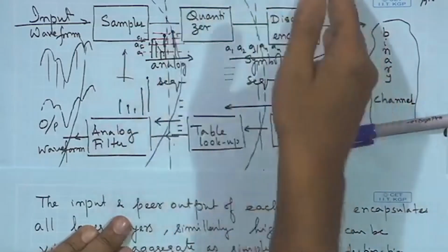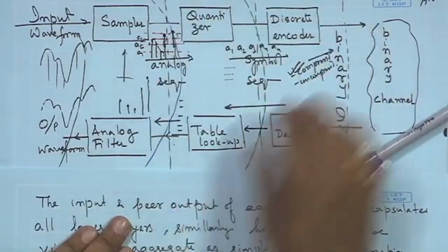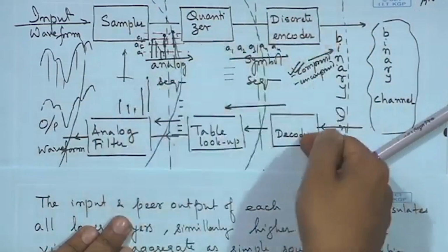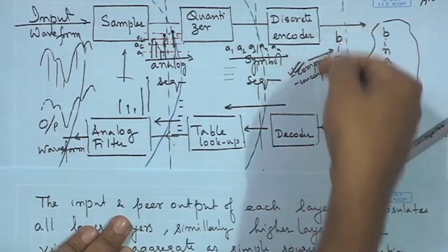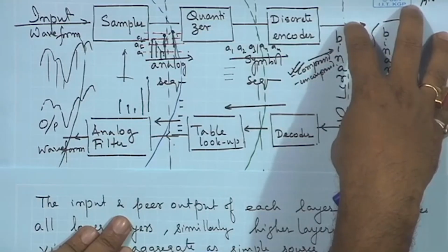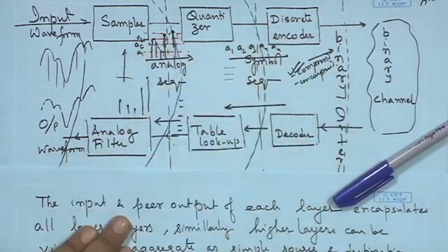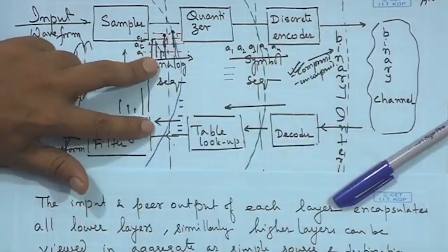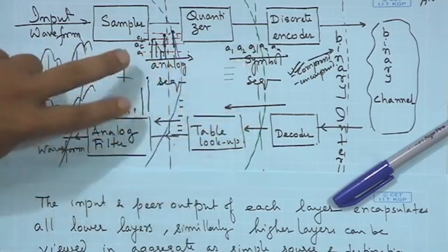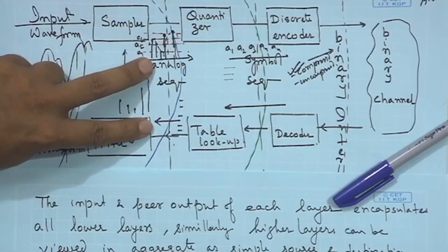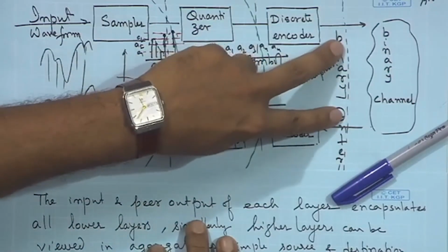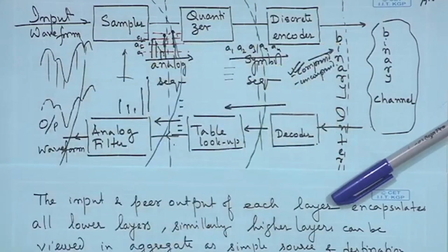Similarly, if I put my boundary point here, I would say that it is some source which produces a binary signal, and some destination which takes binary. So I can compare this input to output and say what kind of channel this is, how much percentage of error there is. Similarly, I can compare here and say what kind of distortion has come in. Here again, since these are symbols, I can talk about symbol errors, I can talk about sequences, the signal to noise ratio, or the total amount of distortion here. I can talk about bit errors and so on and so forth.